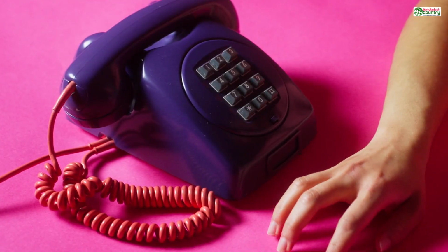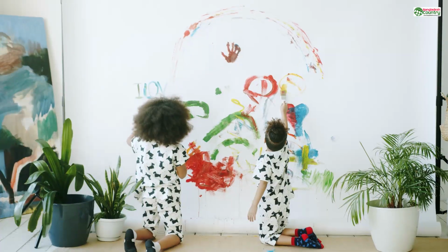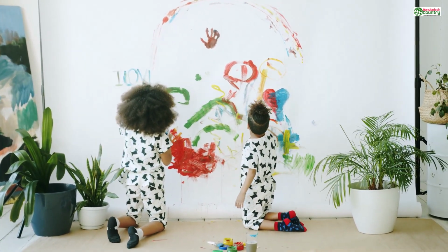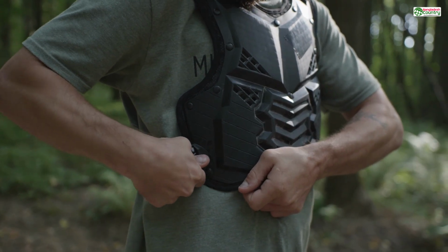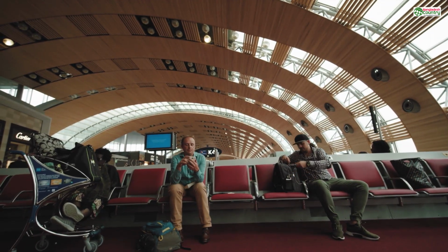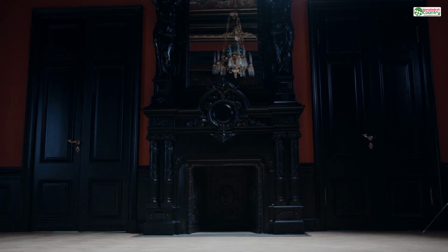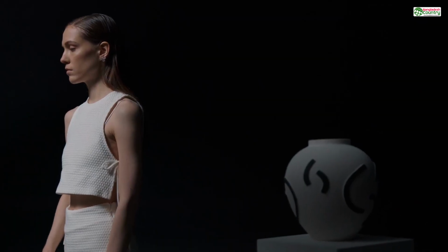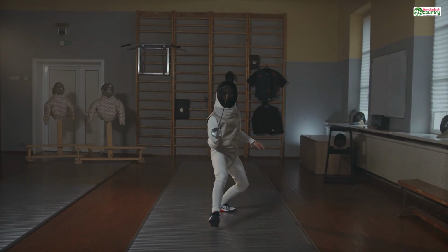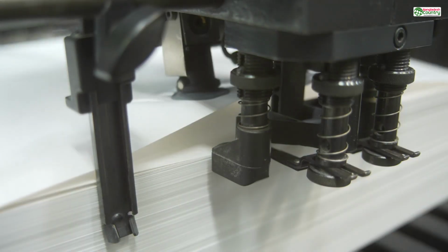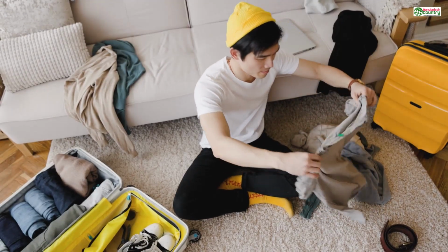Imagine you've spent 40 hours designing a beautiful, intricate statuette of a knight. The armor plates are detailed, the cape is flowing, and the sword is raised high. You upload it, you pay for it, you wait a week, and the box arrives. You open it, and the sword is snapped off at the hilt. The edge of the cape has crumbled away. Why? Because while the main body was thick and strong, you modeled that sword to be a realistic, razor-thin 0.2 millimeters. The printing process couldn't handle it, or the person packing it breathed on it too hard. A heartbreaking but completely avoidable failure.